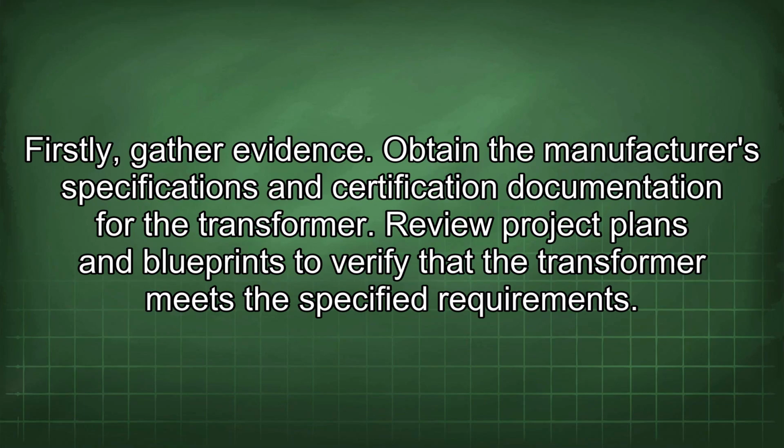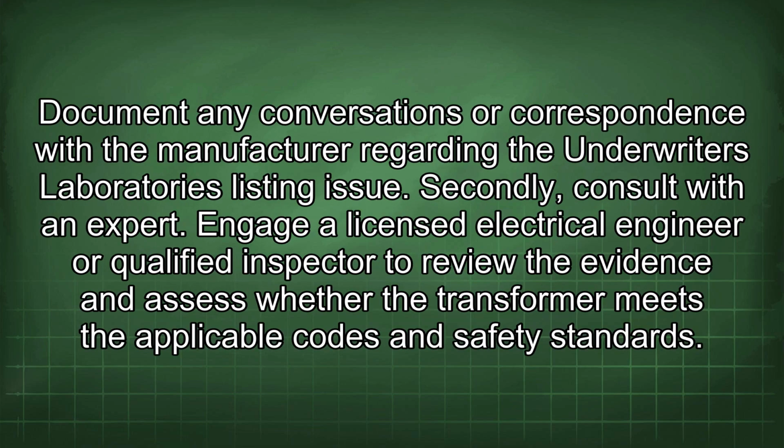Firstly, gather evidence. Obtain the manufacturer's specifications and certification documentation for the transformer. Review project plans and blueprints to verify that the transformer meets the specified requirements. Document any conversations or correspondence with the manufacturer regarding the Underwriters Laboratories listing issue.